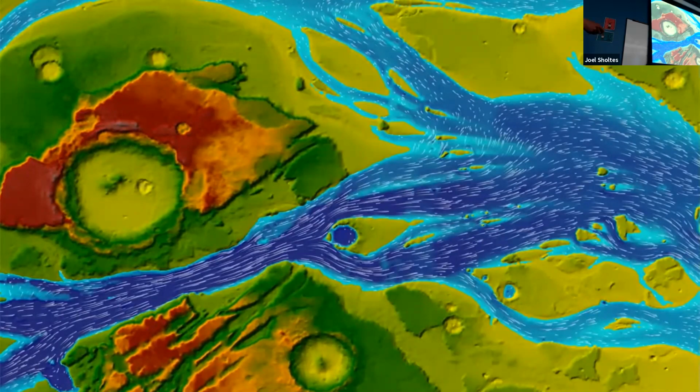And in this two-dimensional model that he made, you can see that it allows flow to split. So flow is going down this way, it's going around this way, it's going around this crater island, it's coming in around here. When we have complex flow paths, side channels, flow cutting across the floodplain, that's when two-dimensional modeling becomes important.